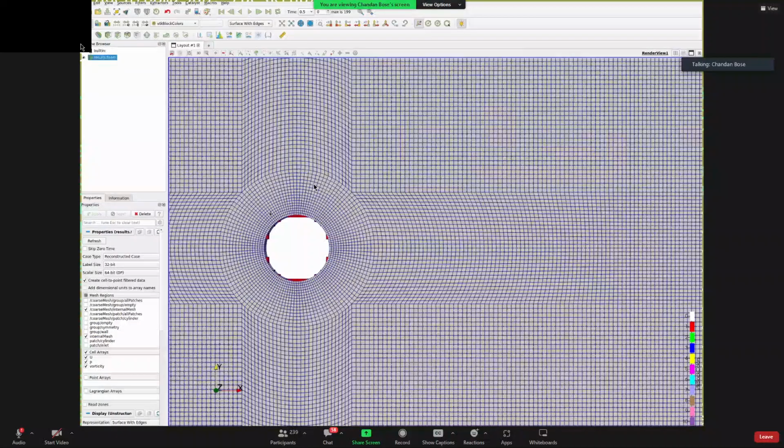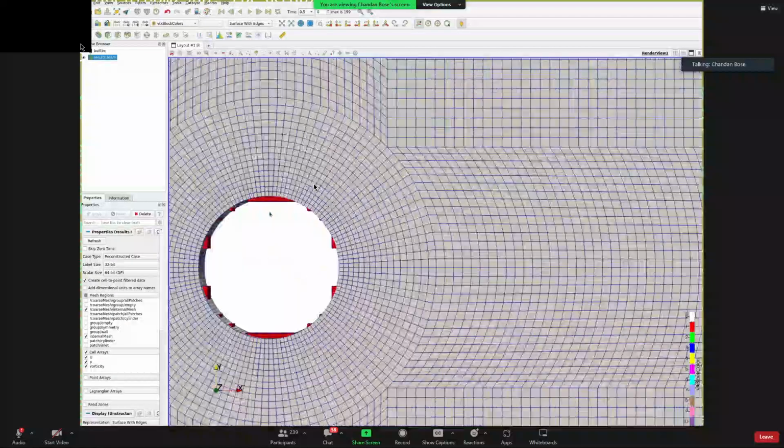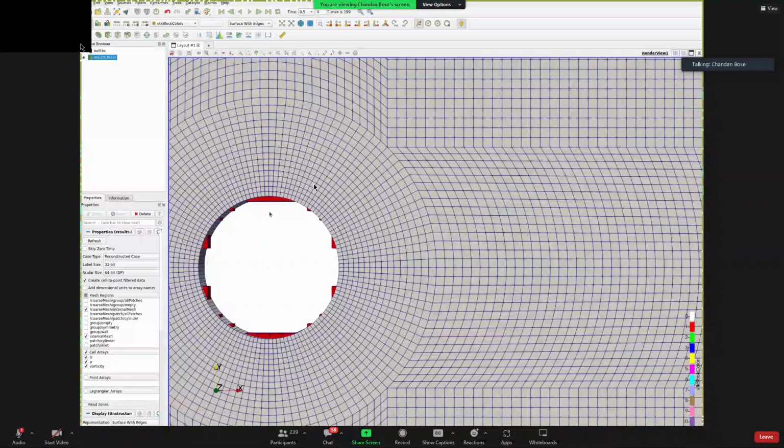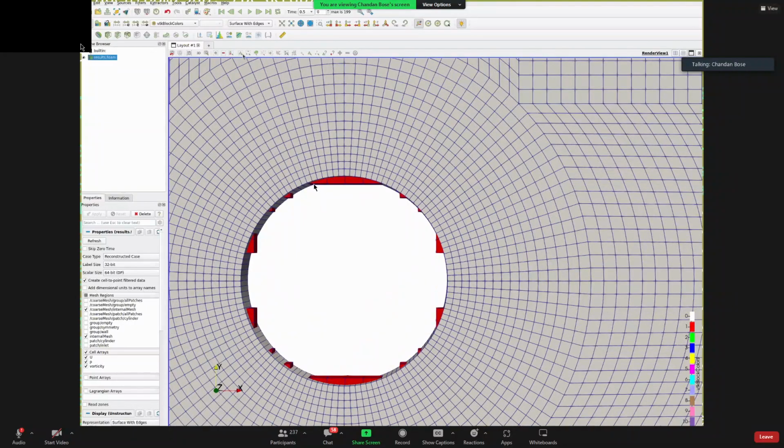Then it cuts the cells within that, depending on the controls that you give to SnappyHexMesh, how many layers and what is the maximum non-orthogonality and skewness you want, etc. And as a fact, you see that SnappyHexMesh is not that good in getting you a proper clean mesh, right? So that is where I would prefer GMSH or Salome, or if possible using blockMesh to make a clean mesh.